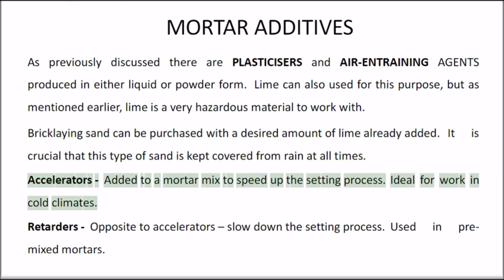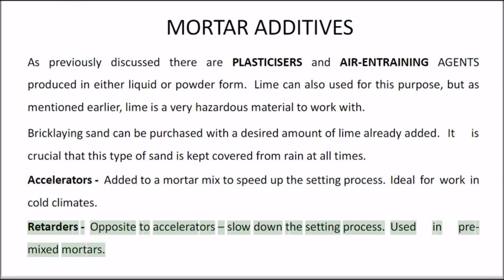Accelerators are added to a mortar mix to speed up the setting process. Ideal for work in cold climates. Retarders, opposite to accelerators, slow down the setting process. Used in pre-mixed mortars.